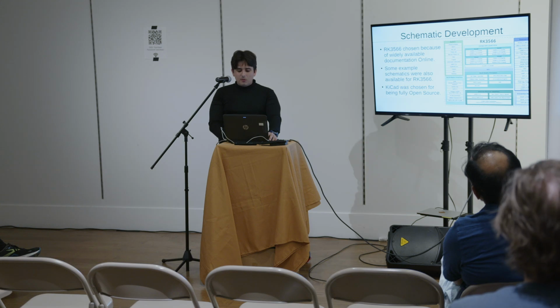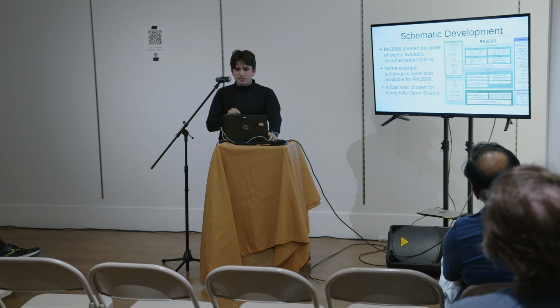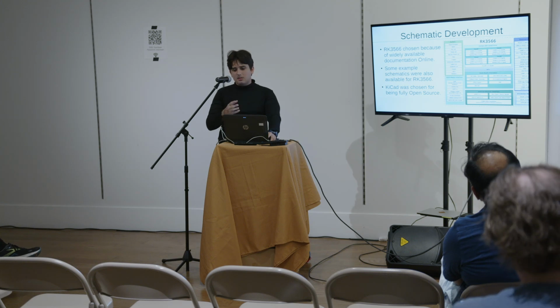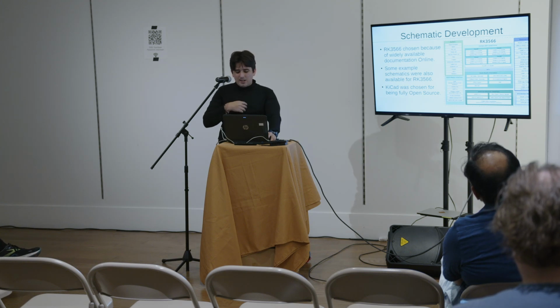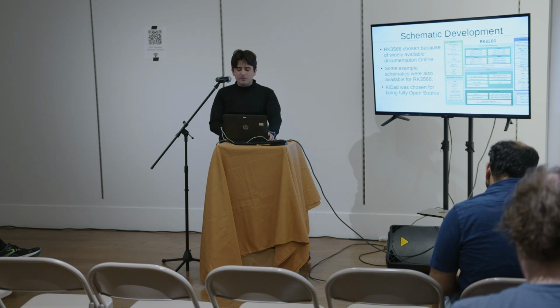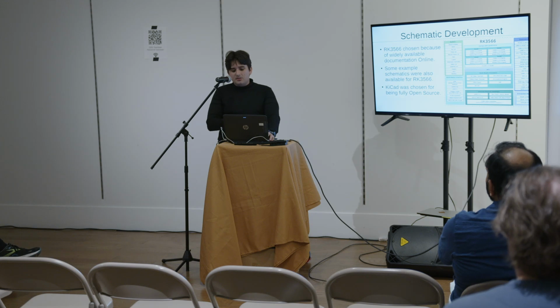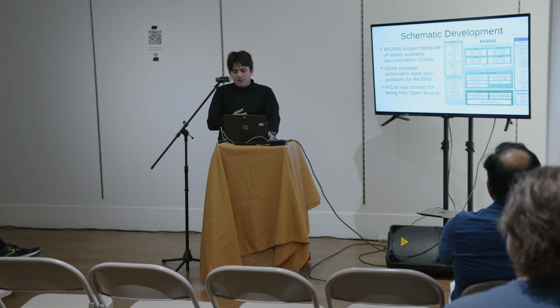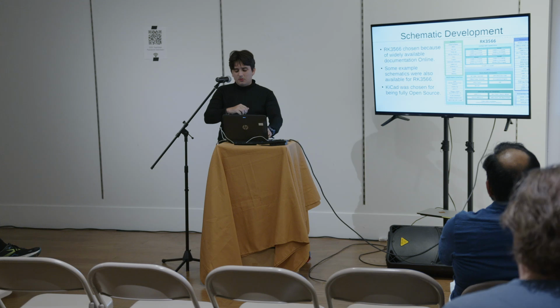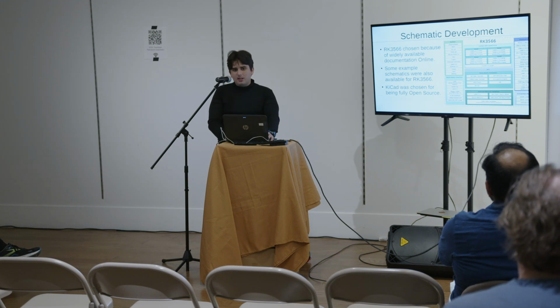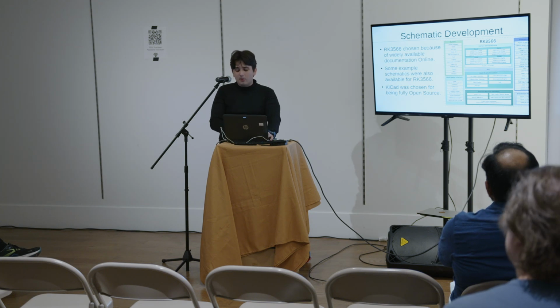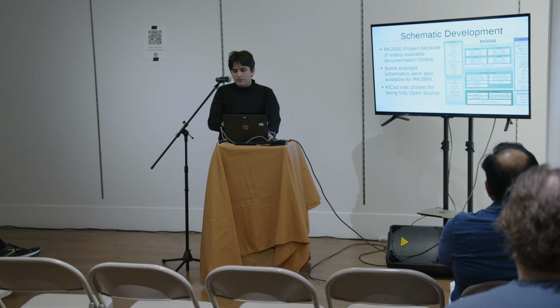One of the key aspects while choosing a microprocessor is that you make sure it's not a microprocessor with very high current consumption, because this can bring out a lot of issues later on. For example, if you have, let's say, a microprocessor with, I don't know, 10 amps of current consumption, this is going to cause you a lot of trouble, because this will really complicate the design of the DC converters when you go to design this in schematics. This is also going to make the PCB layout a lot more complicated. It's also going to make the entire fabrication a lot more expensive.